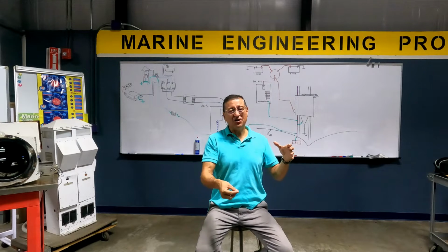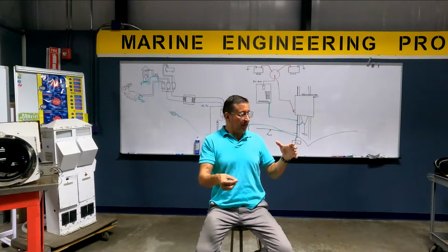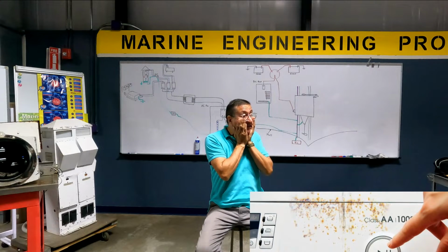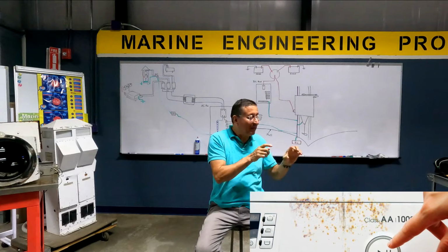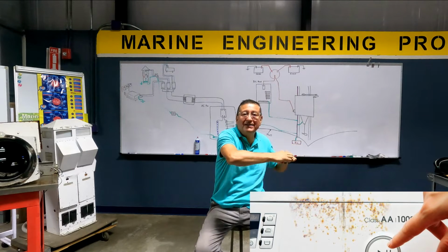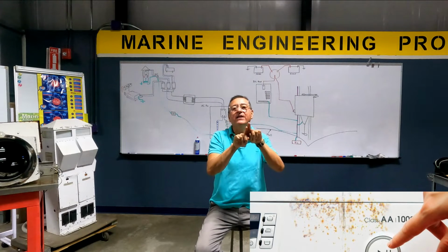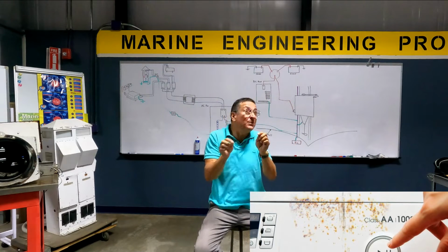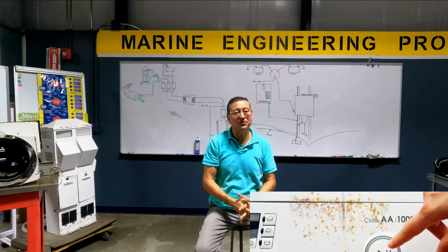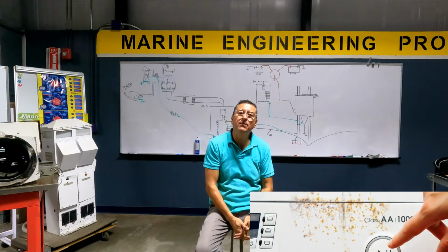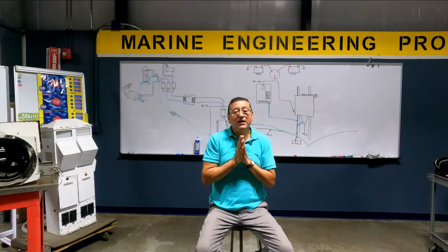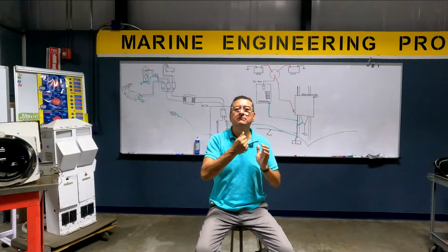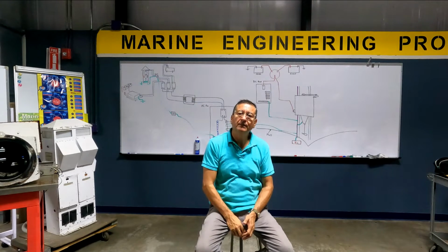The more noble metal destroys the less noble. And in a couple of weeks, wow, the dishwasher is completely eroded, especially around the rivets, where the different metals are together. The humidity in the environment and the electricity accelerate the corrosion process. That's the problem if you don't have bonding. The corrosion starts and moves faster, and your boat is destroyed.